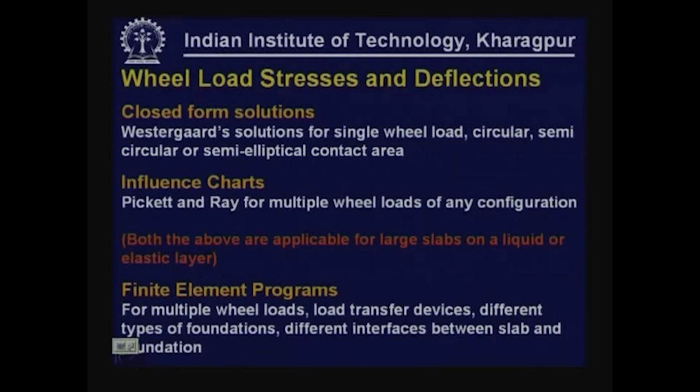Also, finite element programs can handle different types of foundations and different interfaces between slab and foundation, rough interface or smooth interface. So, all these complex situations cannot be solved by standard closed form solutions. So, nowadays most of these agencies normally use finite element programs to solve these complex situations, where you have different types of interfaces, different types of foundations to be modeled, and different load transfer mechanisms. To be able to solve all these problems, nowadays finite element solutions are normally being adopted.